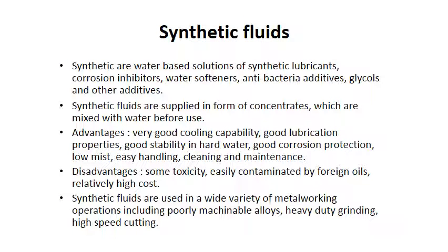Next we can go to the synthetic fluids. Synthetics are water-based solutions of synthetic lubricants, corrosion inhibitors, water softeners, antibacterial additives, glycols and other additives. Second important point is that synthetic fluids are supplied as concentrates which are mixed with water before use.